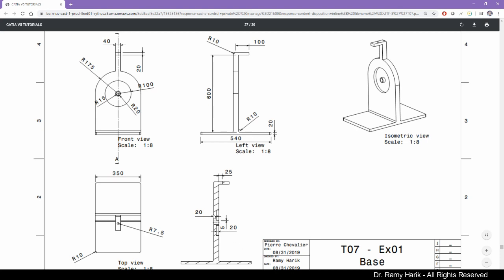So 20, 20, 40. So basically that's a 40. So we have a 40 in here, and that dimension is useless because that 5 is nothing but the difference between 15 and 20. But I mean, it's useful to confirm. Actually, this is very, very useful to take a look at right now, because this is a through hole. This one is 40, the little 5. Then this one in the middle, all of this is 20. Then this one is 40.